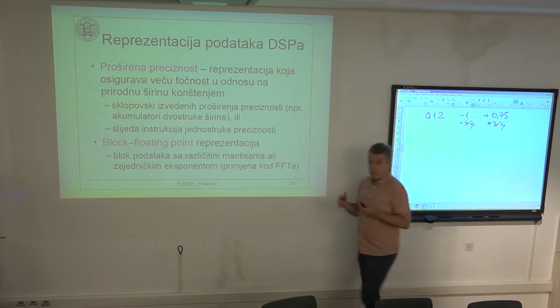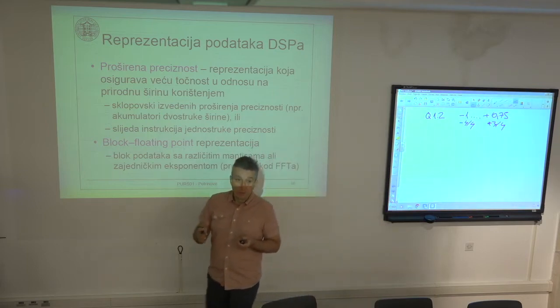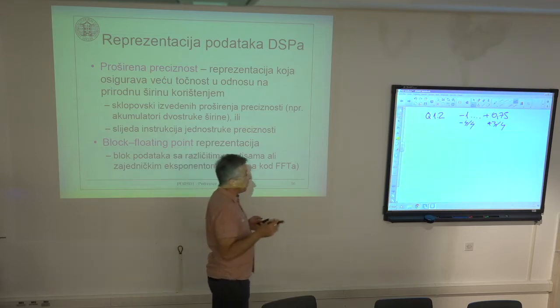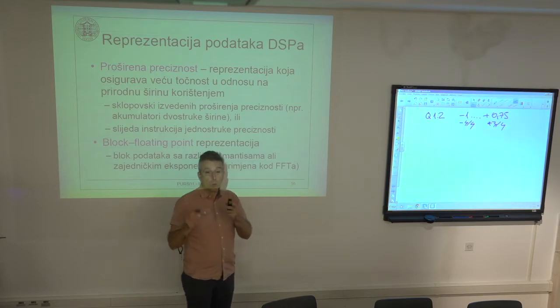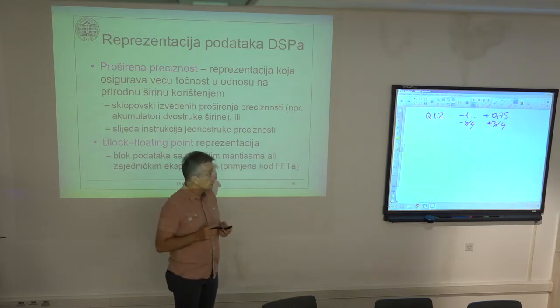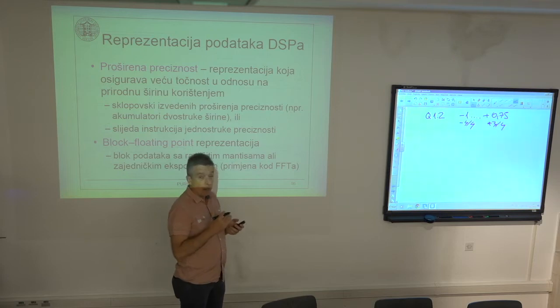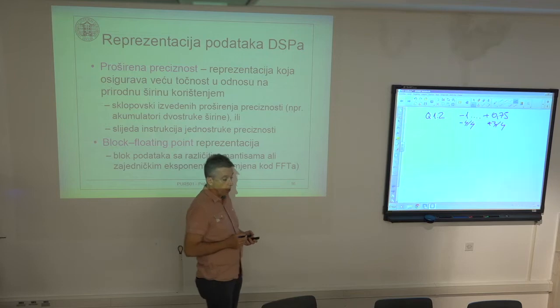So it is just a 2's complement 3-bit value in the range -4 to +3, but divided by 2 to the power of width minus 1. The width is 3, minus 1 is 2, 2 to the power of 2 is 4, so the denominator is 4. Then we have this range, -1 to plus 0.75, and this representation is denoted as Q1.2.